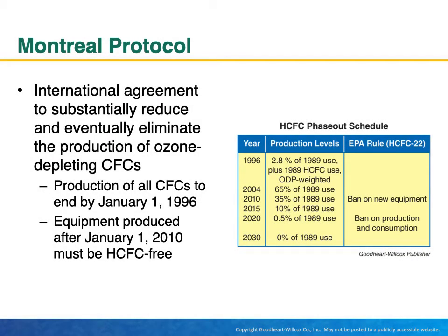The Montreal Protocol is an international agreement to sustainably reduce and eventually eliminate the production of ozone depleting CFCs. Production of all CFCs to end by January 1st, 1996. Equipment produced after January 1st, 2010 must be HCFC free. And on the right, you have the HCFC phase out schedule.